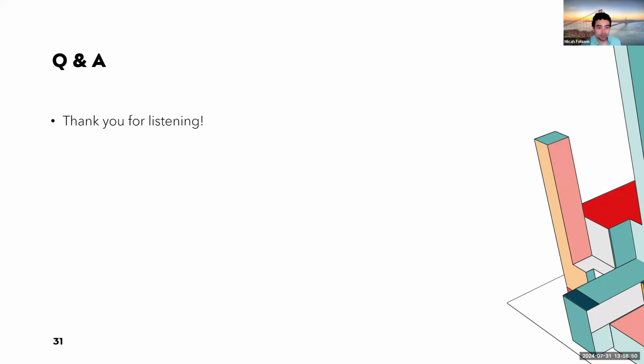Okay, yeah, papers using Geant4 to estimate absolute efficiency. Yeah, absolute numbers, those are tough. Those are real hard. Can we use the output of such a simulation to integrate with commercially available software like Genie 2000? Yeah, that's an idea. I've heard of people working on that sort of thing. I've even heard of people doing a rapid iteration setup where you use a scanning system like lasers to scan your geometry, and then you automatically import that into Geant4 and then run it.